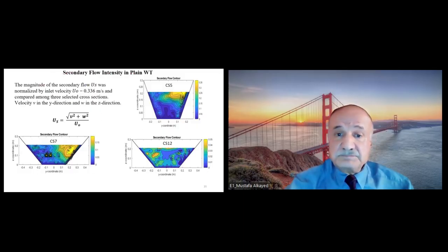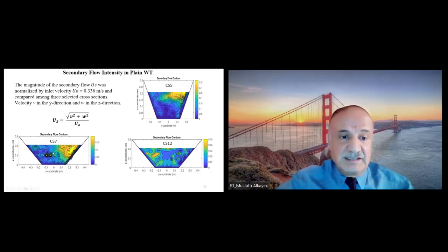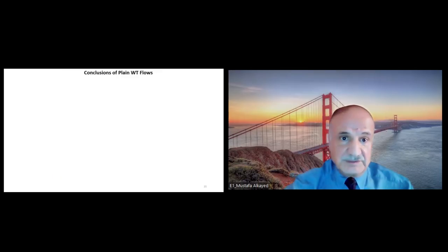Now the secondary shear stress, this refers to the flow going to opposite sides. So this is the flow here, the core in the bottom left side is the eddies. And this is the main flow. And when we go further downstream, we can see that this turbulence is intensive, but it's a little bit smaller. It means it is asymmetric, not uniform. This makes a bigger problem and an erosion risk in the downstream earth channels.